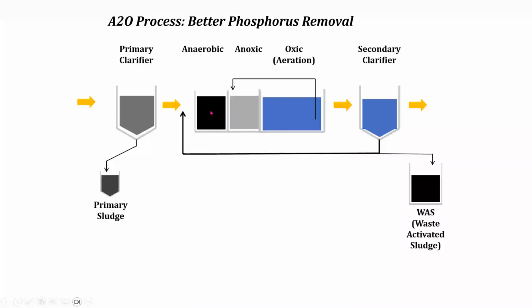So in between this anaerobic zone and the aeration zone, in the A2O process, what's that? Anaerobic, anoxic, oxic. There's an anoxic zone with an internal recycle. Okay, what's supposed to happen here is ammonia is converted to nitrate. The nitrates go to the anoxic zone. The nitrates are feeding on whatever BOD is coming out of the anaerobic zone to remove nitrates. So then the nitrates in the return sludge should be quite low. Influent is almost all ammonia, has no nitrates. So the nitrate coming in here should be low, which should then turbocharge the performance in the anaerobic zone because there's little nitrate interference. So that's the strategy.